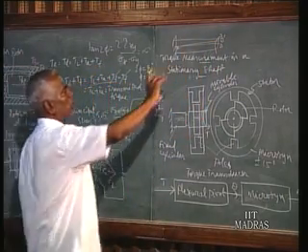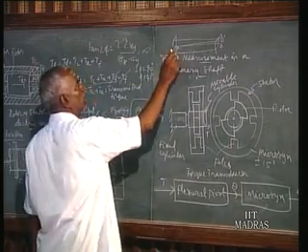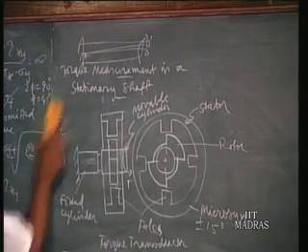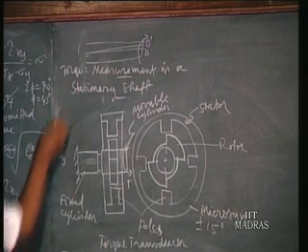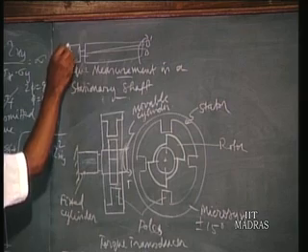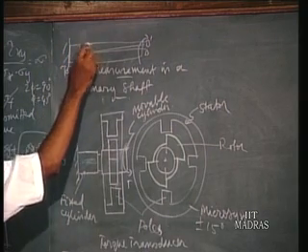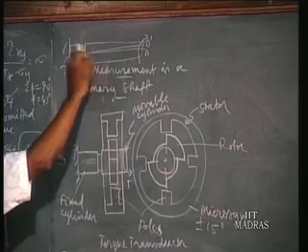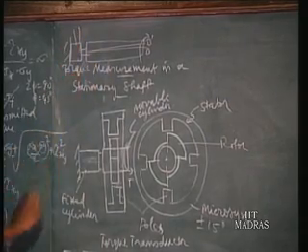If you want to measure this torque on twisting, then instead of fixing the shaft to the wall, you can as well fix it to the transducer. Now the shaft is fixed to the transducer, so when you apply the torque, the transducer gives the signal. So it is an easy method.